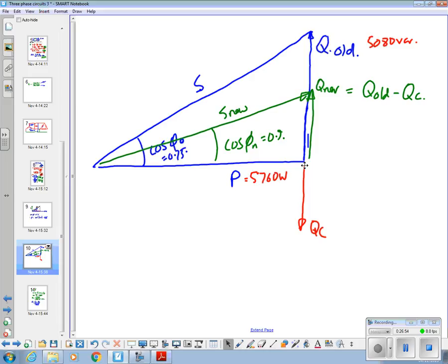So that's where that is, phasor diagram or power triangle wise: we've added some capacitance into the circuit, pulling this S line down a bit, and we got a resultant new overall Q that is the old Q minus what we've added from the capacitor. Yeah? And then you'll go through the rest of the calculation. So here we can find Q new from the triangle, which is what Matt did anyway. Yeah.